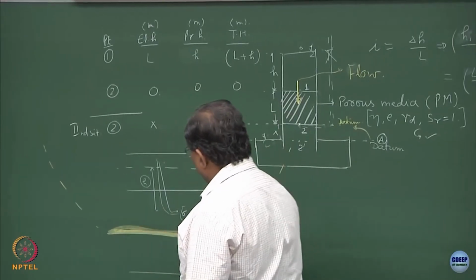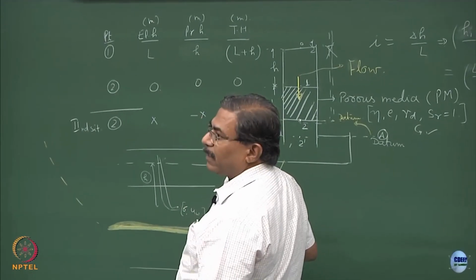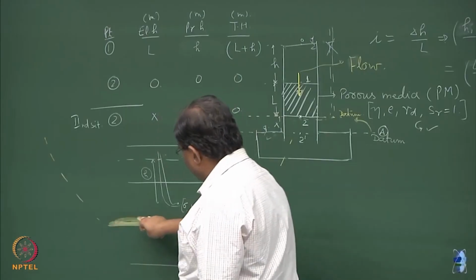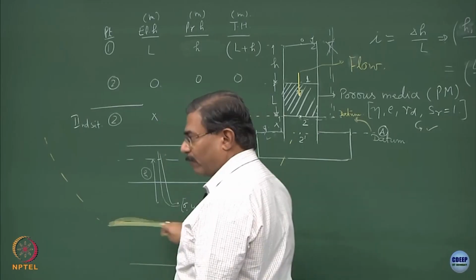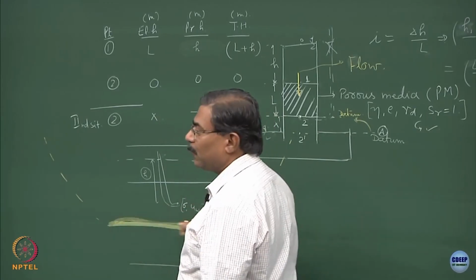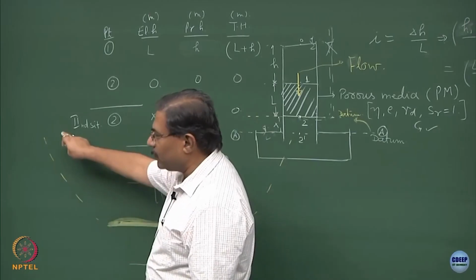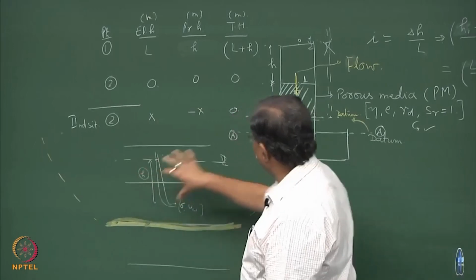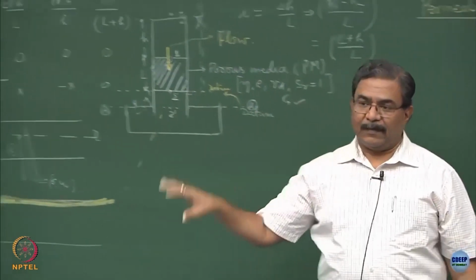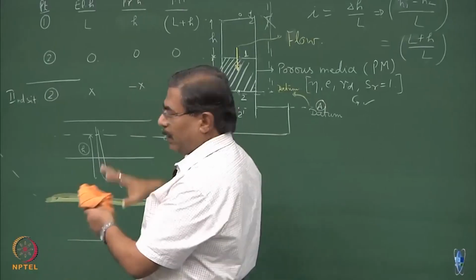Now, at each and every point here, this is what is known as a filter. I have included a sand layer. In case of your gas hydrates, you are doing hydrofracturing and you are making this system more permeable. This is connected to the atmosphere, and hence the pore water pressure at this point is going to be 0. Then this situation is identical to this situation. Is it okay? Any questions? Is this clear? So, this is what the engineered system is. I hope this point is clear.